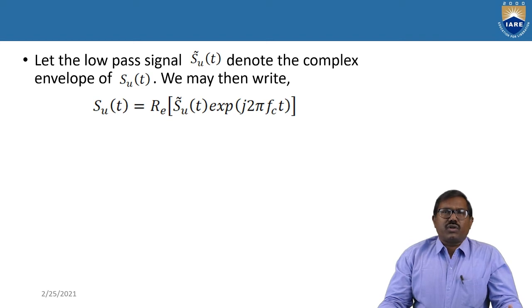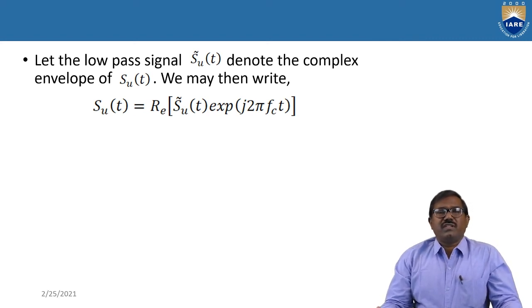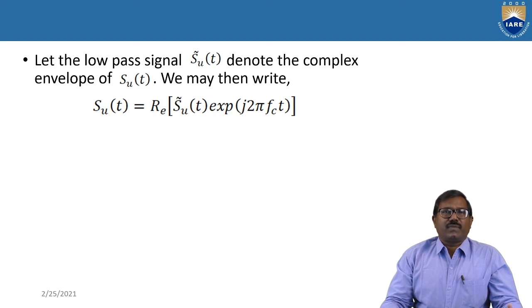We may then write s_U(t) equal to the real part of s̃_U(t) exp(j2πfct). So here we are taking the real part of this complex envelope of s_U(t).